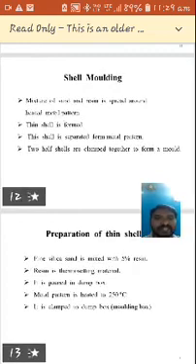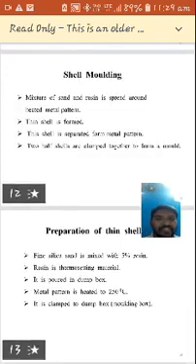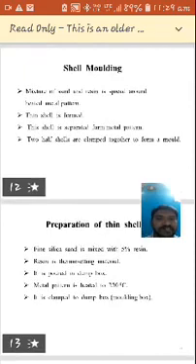After heating that metal pattern, we apply this mixture of sand as well as resin over the metal pattern. Then, when it is applied over the heated metal pattern, a thin shell is formed. From the metal pattern, the thin shell is separated. So the two halves of shells are clamped together to form a mold.